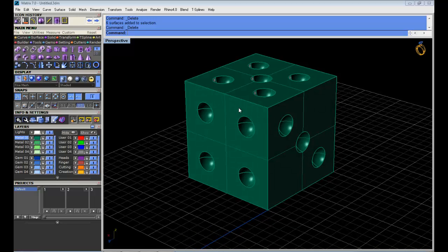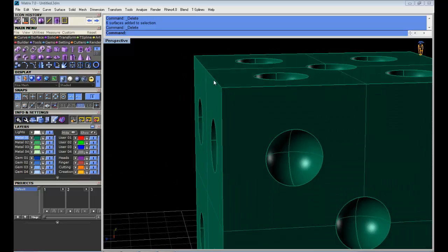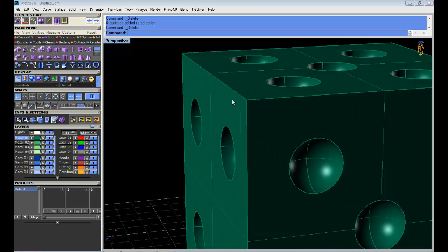what's next? You see now the edges, they are really sharp. We want to make them slightly smoother, so we can use this command on the solids menu. It's called fillet edge. By default, it's going to be set to 1. That's quite too much in this case. We need to change this current radius. Just click on it and type, for instance, 0.15.